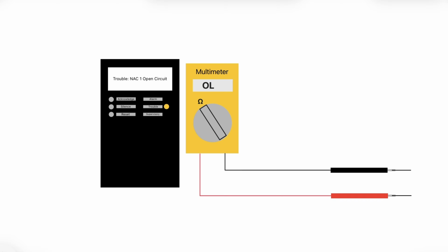Simple, right? Now, the fire panel works the same way. When the fire panel measures the lack of its required resistance value, with its internal multimeter, it says, "Oh, no. I'm not measuring my end-of-line resistor. It's not there anymore. There's an issue on this circuit. I'm going to beep and display a trouble message to get a technician's attention."